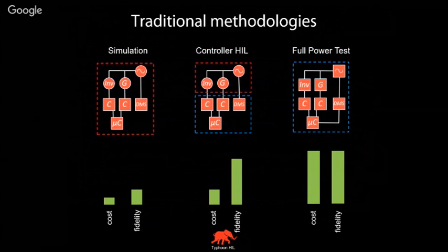This means that we can now use very fast computational platforms to solve some very complex equations that describe particular systems, and we can interface real control, real protection devices, real FACTS devices, all these smart layers, all these software layers of the network, to a completely digitalized power stage. This concept is now known as controller hardware-in-the-loop.